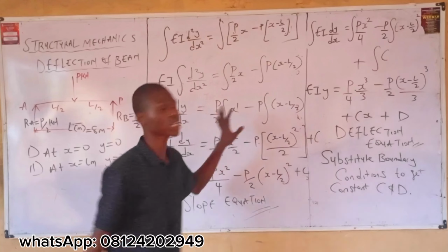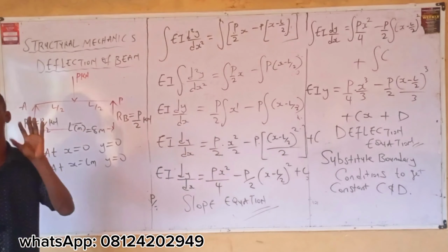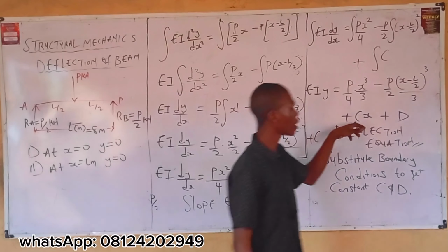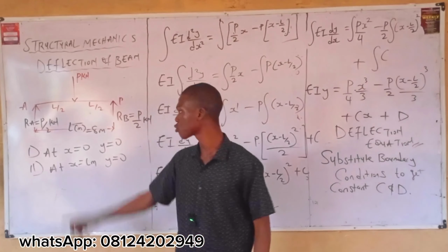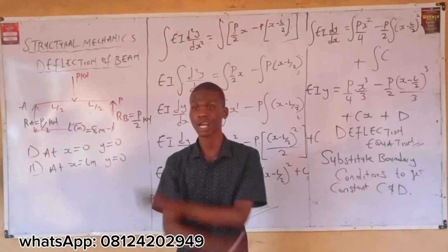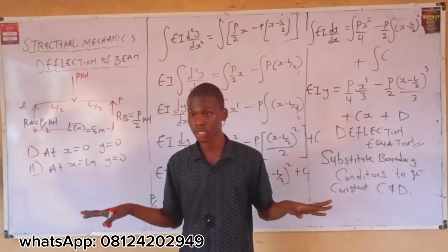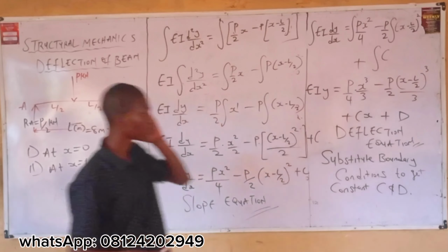As far as a simply supported beam is concerned, this is how you take your boundary condition. Check this beam. You need to get this clearly, because this is the stage whereby you confirm the value of C and D. If your conclusion on your boundary condition is wrong, you can never get it right, after all the stress in solving. Now, please pay attention here.